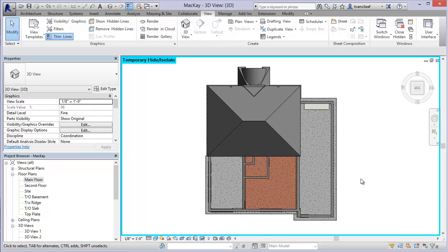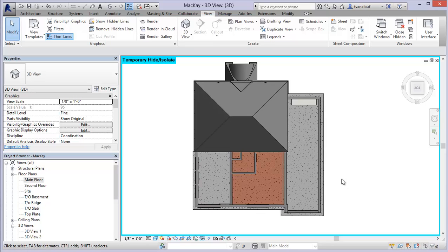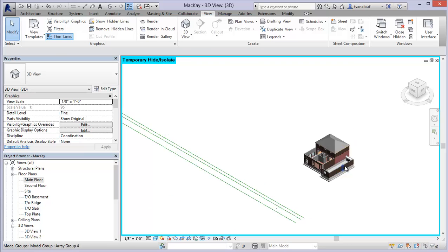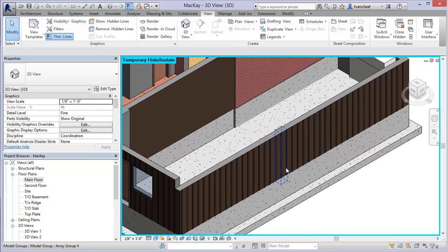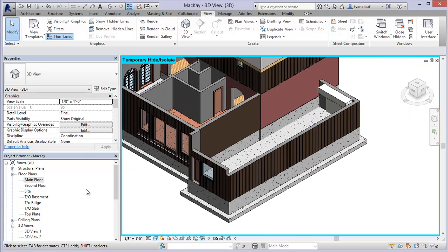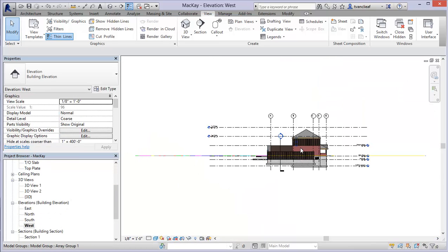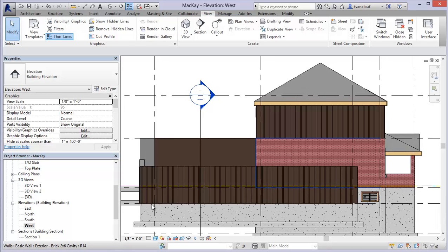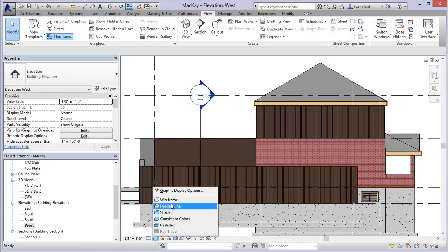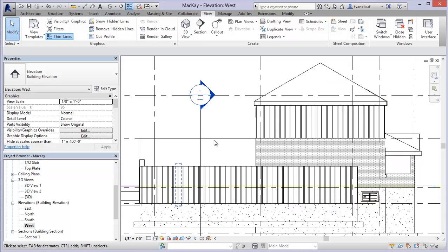So what I'm going to do essentially is you need to create a 2D sketch on a plane or a face, and so I'm going to use the face of this garage here. So actually, why don't I go to the west elevation? So this should be a good place to do this. I'm going to find the hidden line mode so things go a little bit quicker.